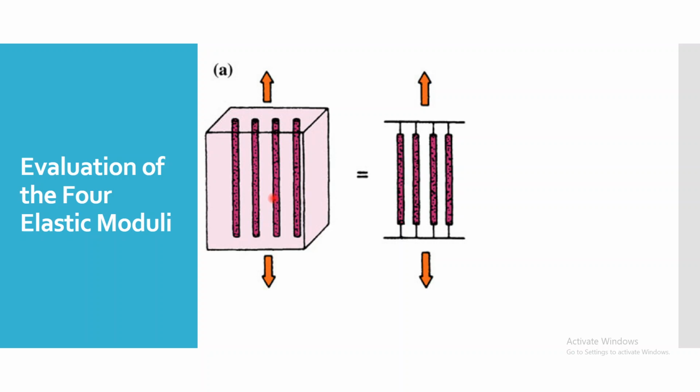That's why we should find out the Young's modulus in different directions. Okay, so if I consider this figure itself here, as we observed from the previous theories, fiber has its maximum stiffness in the loading direction.